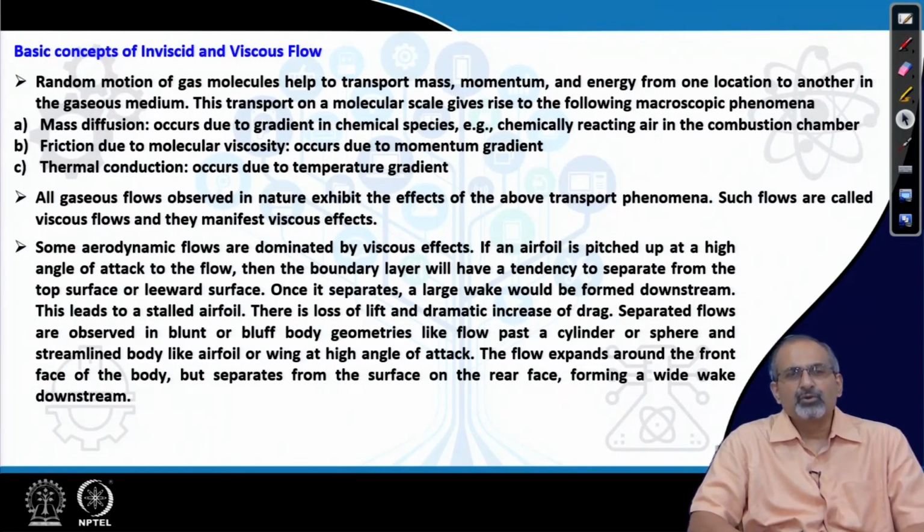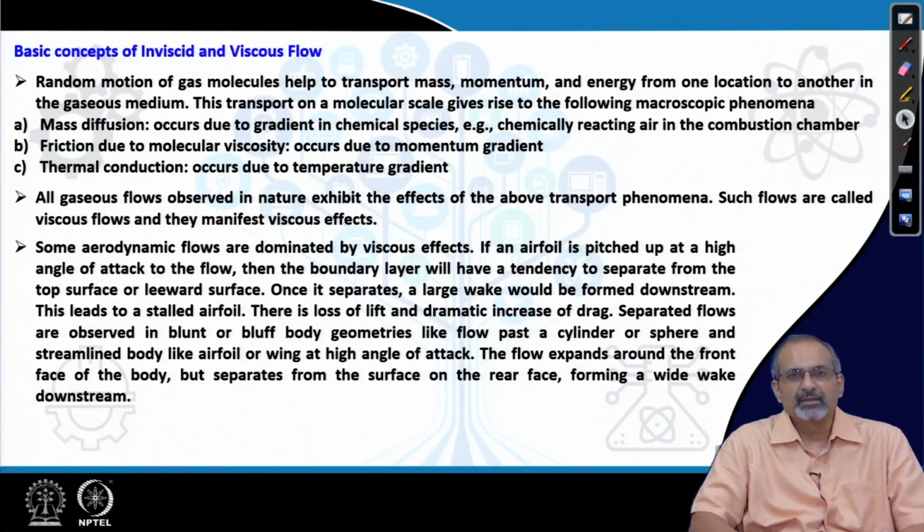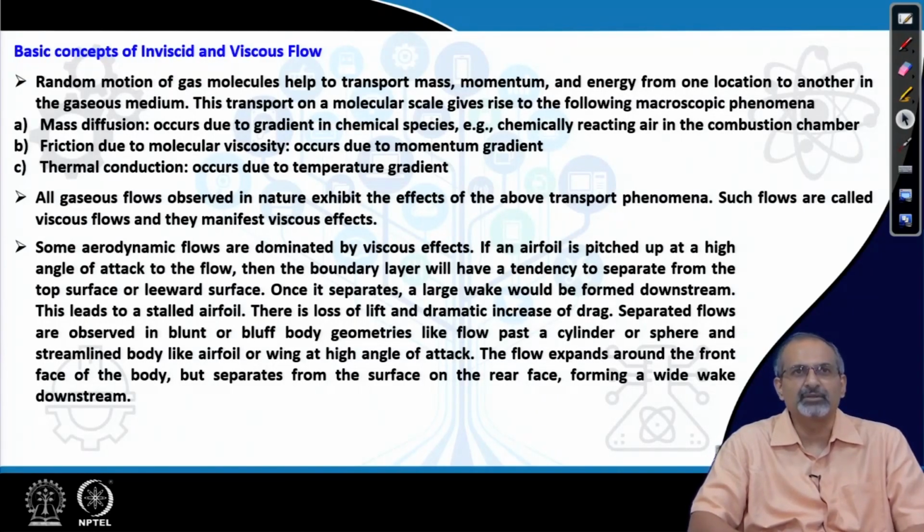Some aerodynamic flows are dominated by viscous effects, and that is of interest to us. If an airfoil is pitched up at a fairly large angle of attack, then the thin layer affected by viscous effects around the airfoil has a tendency to move away from the surface and separate from the surface of the airfoil, especially on the top surface, which we call the leeward surface.